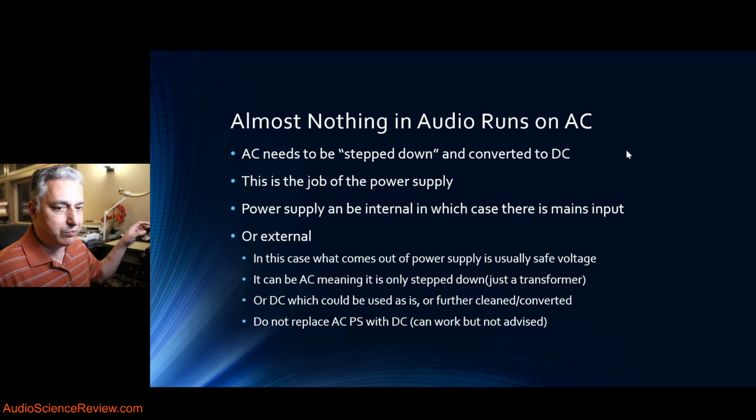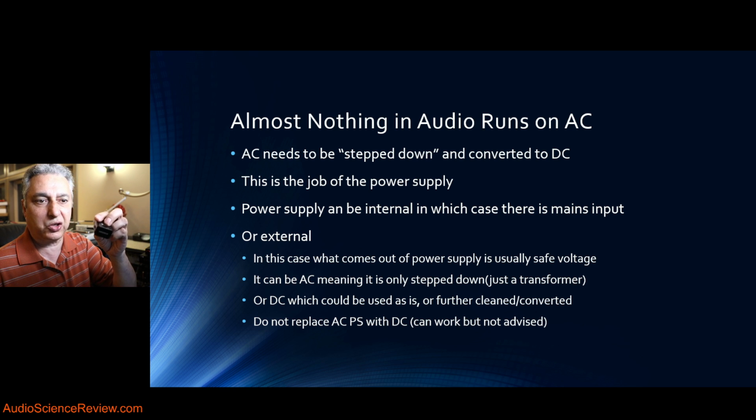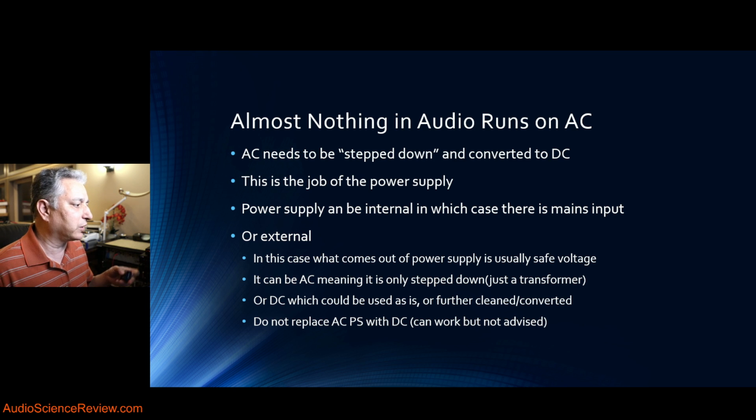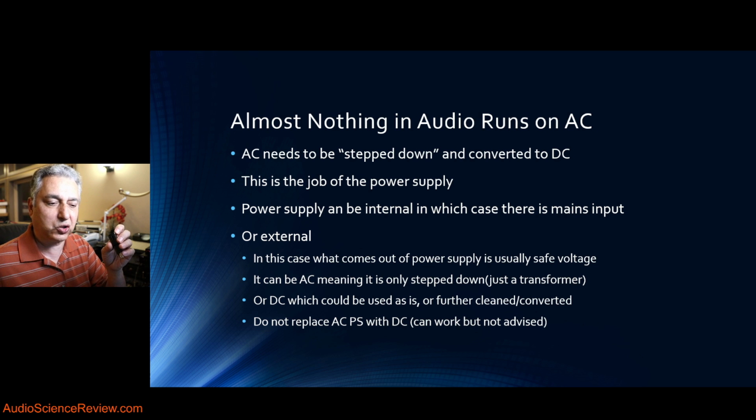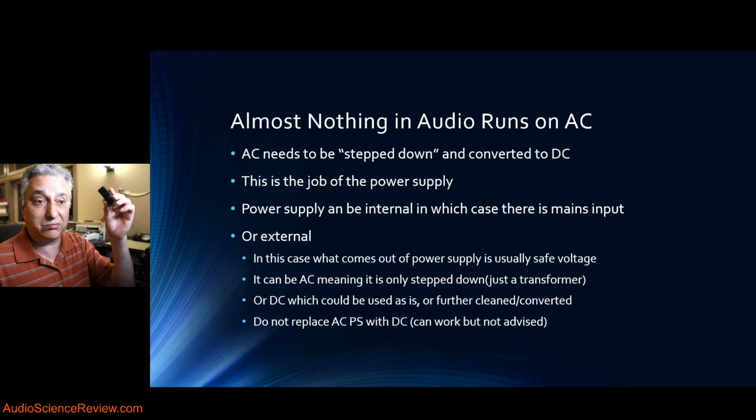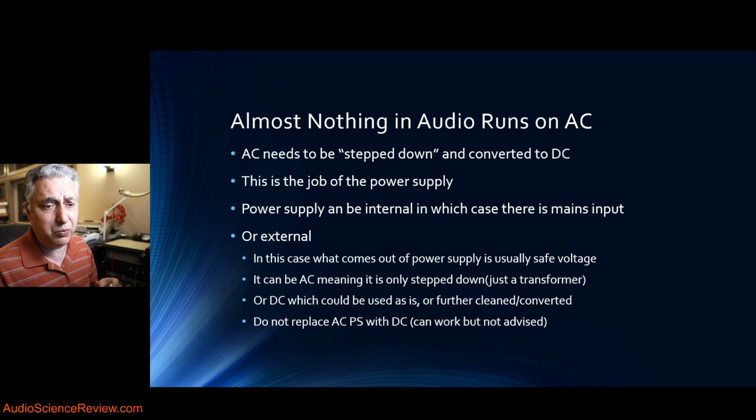It can also be DC output. Most common is the USB chargers for your phones. They put out 5-volt DC in the form of a USB plug. And generally, though, this is not used as is. Internally, a lot of audio devices require multiple voltages, not just one. So they take either one of these outputs and then convert them again to whatever they need. And/or they may clean up the output of this thing. This is designed to be pretty cheap, and you may need a much higher precision power supply inside that's less noisy and what have you.